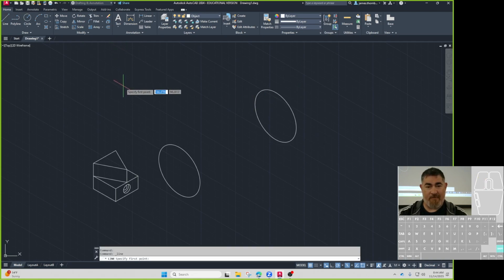So let's see if that works. So if I right click, tangent. Uh-oh. Was that tangent? That is not tangent. Not even close. Yeah. Okay, never mind. But you have the right idea. I need to draw a line that is tangent to the arc, but the O-snap doesn't work.